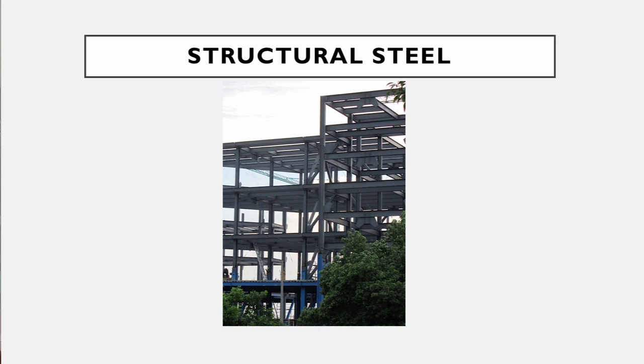Now there's three types of steel that we really use in civil engineering, and there's going to be what we call structural steel. These are the big wide flange beams, the tube steels, the channels that are all that hot rolled steel. So it's shaped while it's hot, while it's still in that red hot. You can pound it or force it through rollers to get the I shape or the H shape or the C shape.